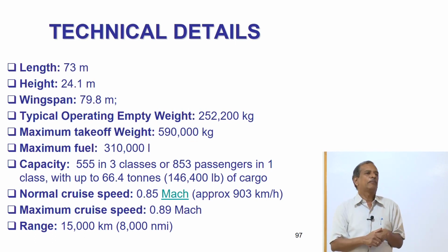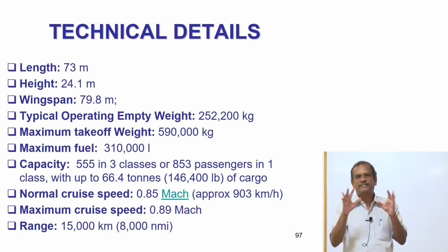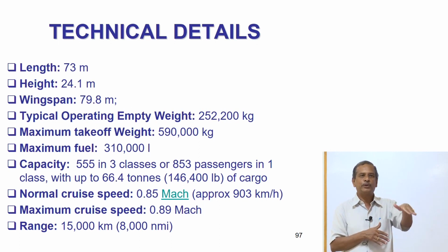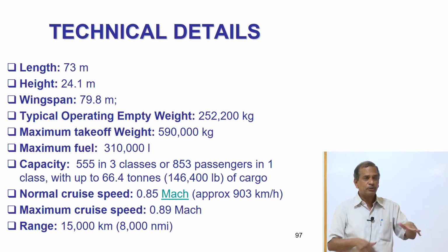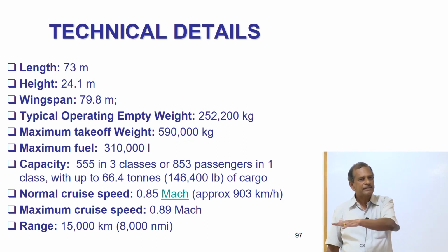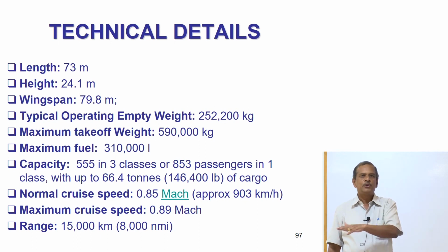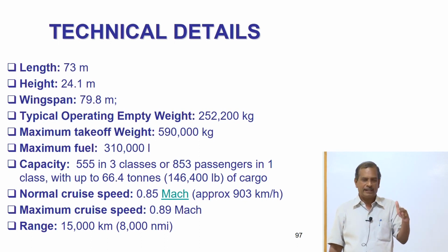The duration of the load application on a runway is only a fraction of a second because the aircraft lands at 200 to 250 kilometers per hour speed. But it reduces speed when it goes to exit taxiways and crawls at a low speed in a taxiway. So the deterioration in a taxiway will be more than the deterioration in a runway. So how do I design a sustainable taxiway? What material? What type of pavement, what combination of different layers is again a challenge.